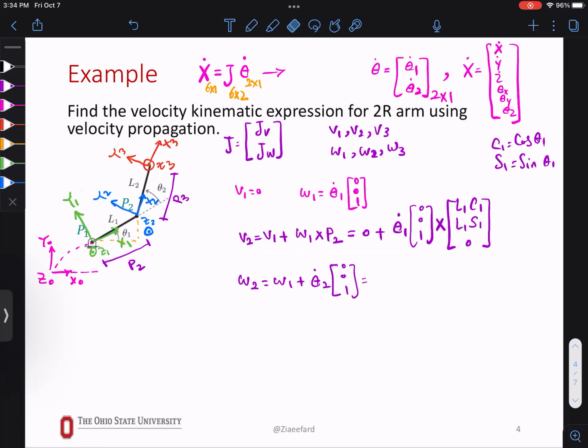Yes. So you're going to replace that there. So we basically wrote an algorithm for our problem to solve for the Jacobian, for velocity kinematics. Now, since the direction of your z's are the same, I can factor out the 0, 0, 1 vector, right? And add the two velocities together. Does this operation make sense to you when you look at the robot?